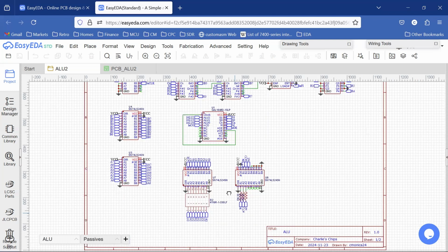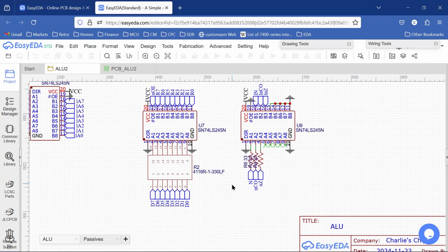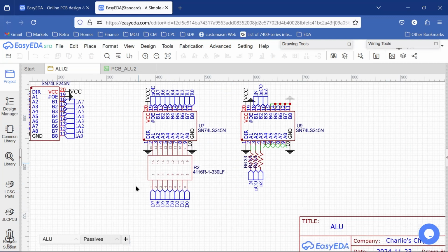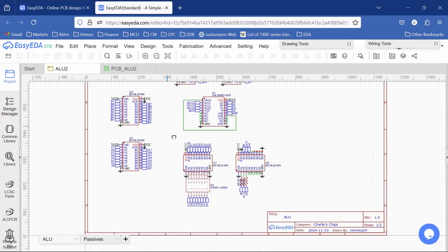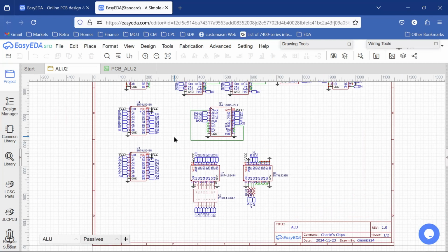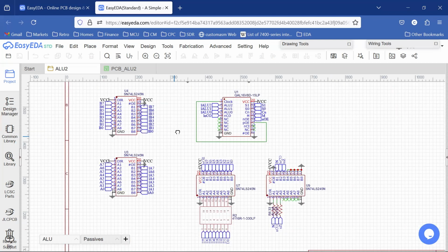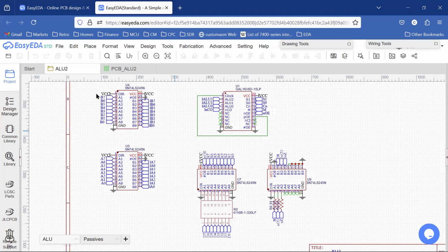And this schematic is virtually identical to our digital simulation design. The major difference here is the addition of our resistor networks that we've added for impedance matching to our data bus. And besides that, I've done some of the typical changes that I've done in the other cards to improve trace routing, and I've reversed the directions of most of the bus signals.